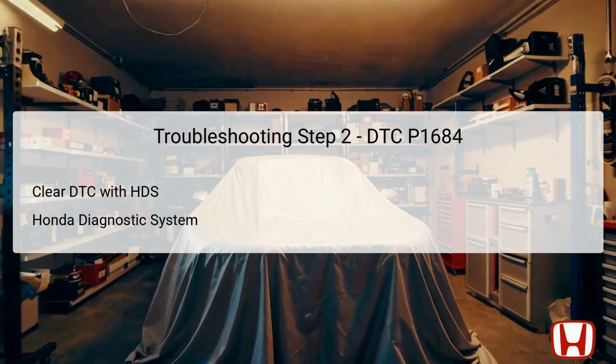In the second troubleshooting step, the next action is to clear the DTC using the Honda Diagnostic System, HDS. This system is a specific diagnostic tool designed to interface with Honda vehicles, allowing for efficient communication with their onboard computers. By clearing the DTC, the technician resets the vehicle's diagnostic computer so that any immediate issues can be identified accurately during the subsequent steps.